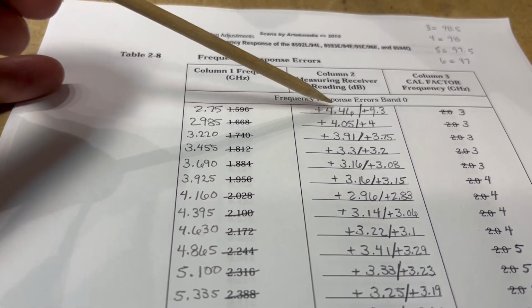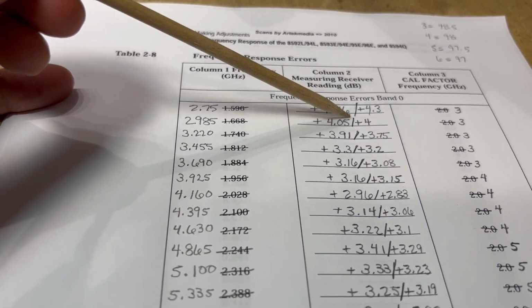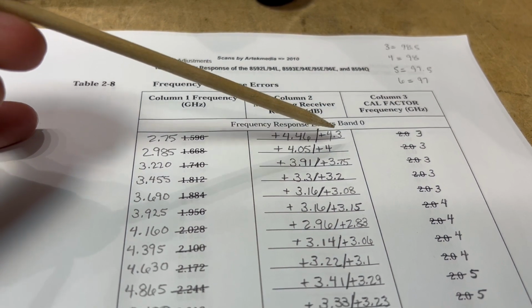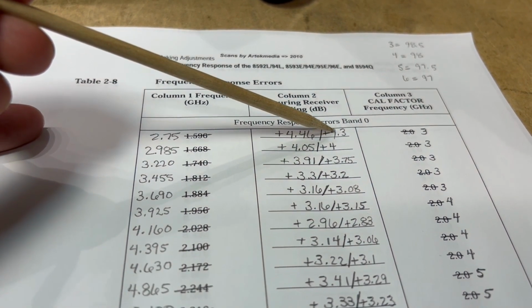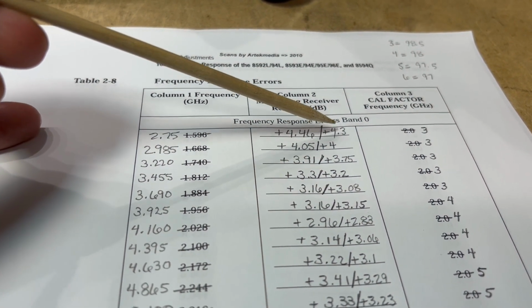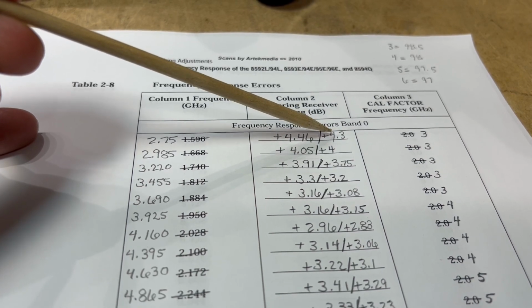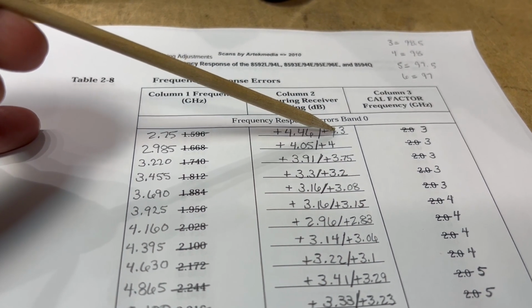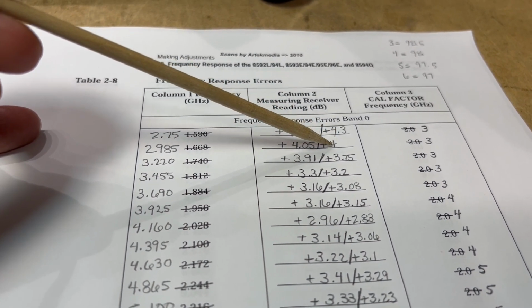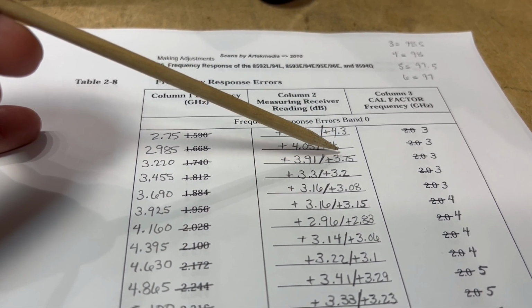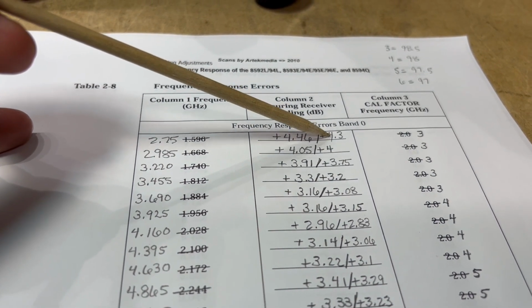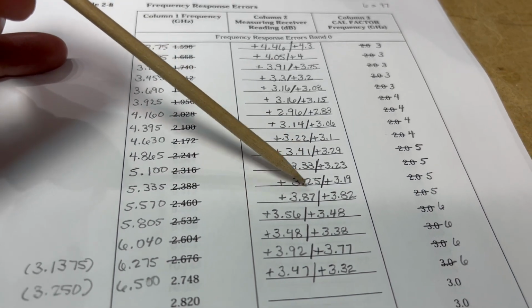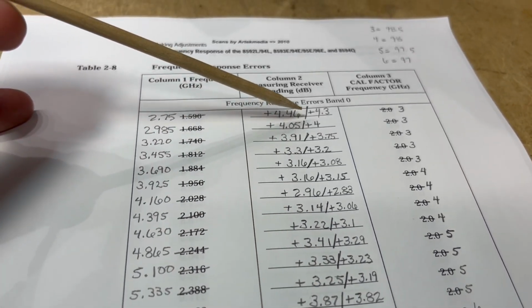I would look at the low and the high and take a value in the middle. With the 8672A, I didn't really see that at all. Once I got the power level adjusted, the relative power level was pretty stable. It wasn't a whole lot of going back and forth. So I feel like I have a little more confidence in the second numbers, and those are the ones I'm going to use for the correction factors.